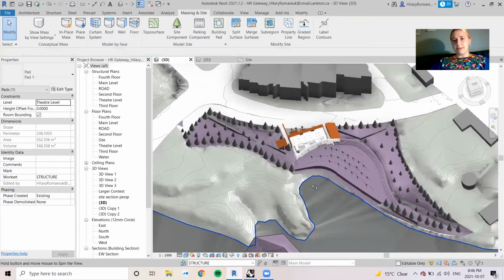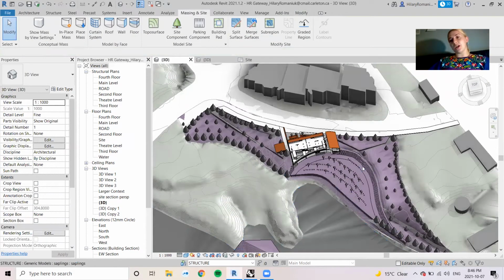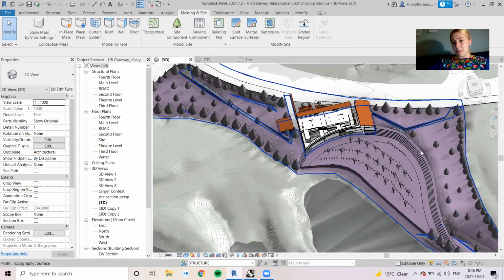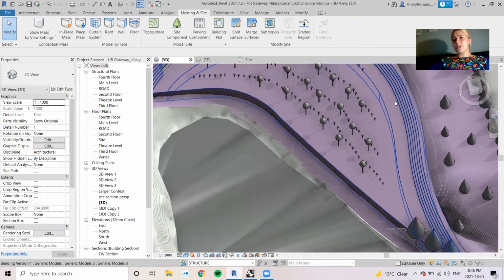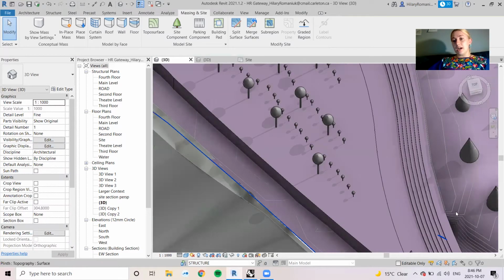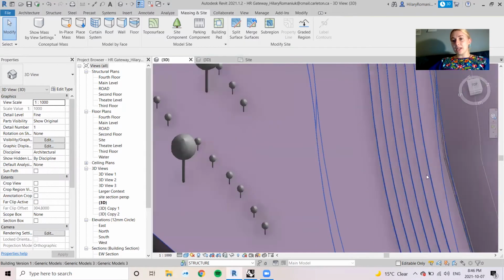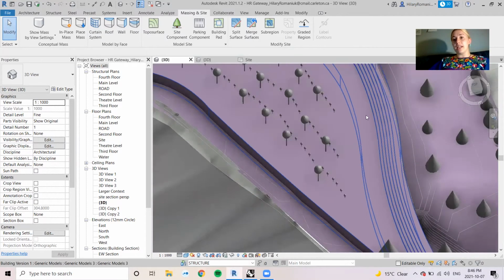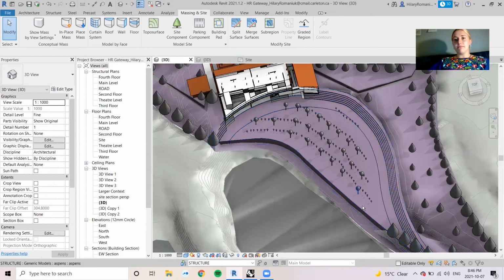So I just wanted to share that. Lastly, for creating topography, you don't have to use the Topo tool. So if you want to create something more regular like this shape here, this would have been a pain to create using the Topo tool, because I would just be pulling and pushing points down and up. So to get a crisp edge like this, it just would not work.